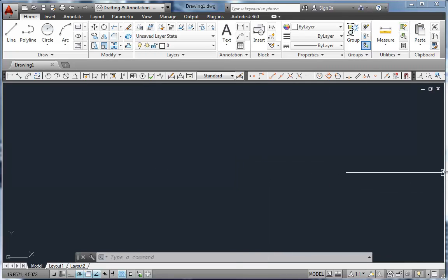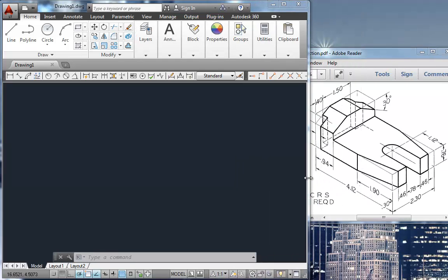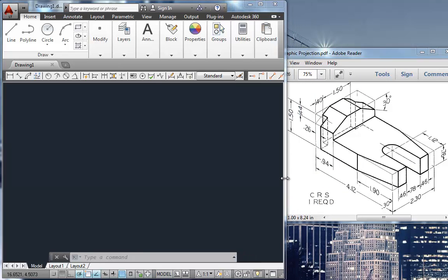And I'm going to slide this over now and expose behind here a little multi-view drawing problem, just to demonstrate from a clean sheet what this would look like. So here's a part. It's shown in 3D, and we have a pretty standard rule of thumb here in our classes for 101, and that's typically when I give you a pictorial drawing like this, this will be the left side view. Looking down on it will be the top view. I'm sorry, this will be the front view. Sorry for the confusion. The front view looking in towards this face.